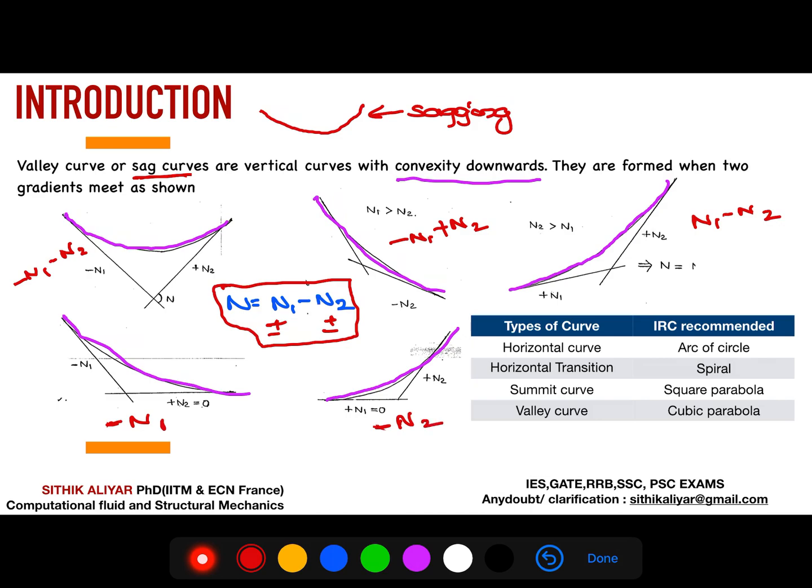Mostly we are getting a negative sign. The summit curve will never go to a negative sign. For the valley curve you will expect either small positive values or, in most cases, a negative answer, but don't use that negative answer in the formulas. The negative answer says that it is acting in a downward direction. It is just a directional point of view, showing in which direction the deviation is happening. I hope I made the deviation angle for the valley curve clear.